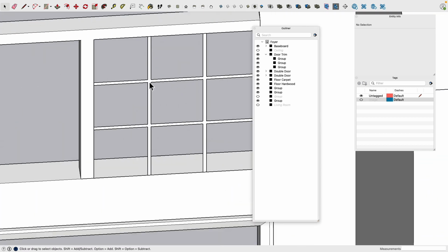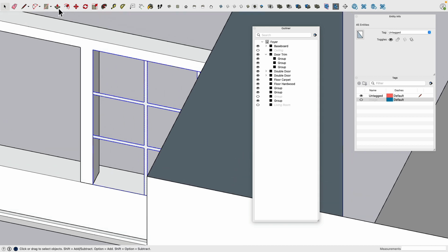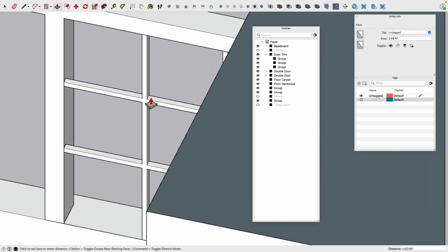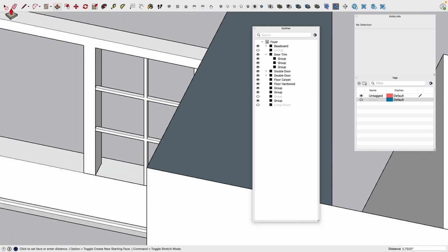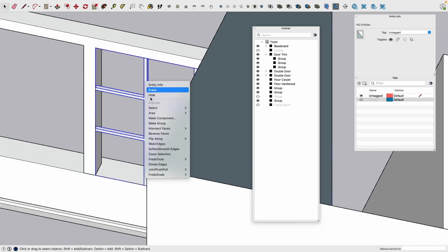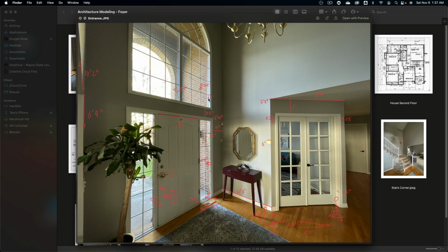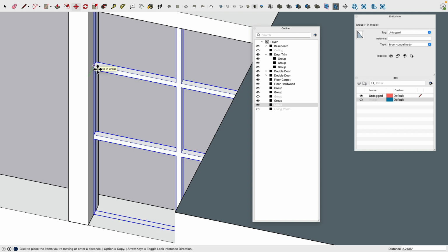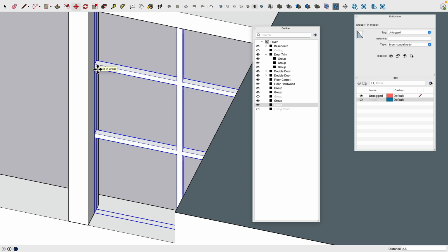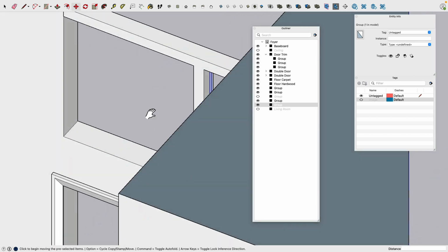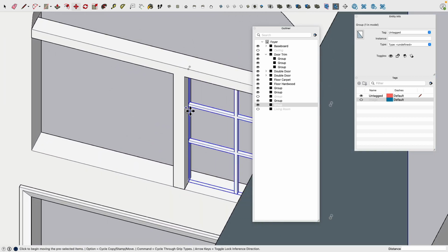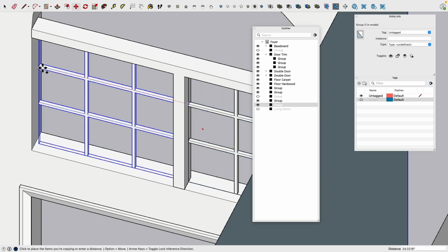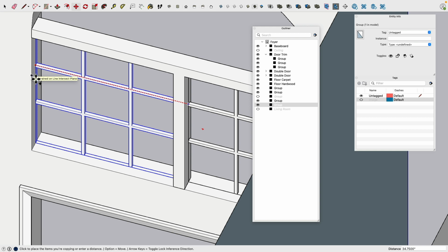Quick clean up. This whole thing we extrude by how much? 0.75. And then we will make this a group. Okay. And 2.5 this goes in along the y-axis, sorry. It's getting really late. I need to go to bed soon. My brain is shutting off. We make a copy with the move command along the x-axis and pressing the alt key, click.